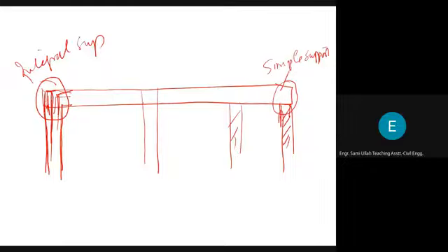If the support is integral, so for this exterior beam, this span, this value of the positive bending moment will be 1 over 14. Okay, and for this span where the support is simple, the positive bending moment will be 1 over 11. The bending moment diagram will be like this.